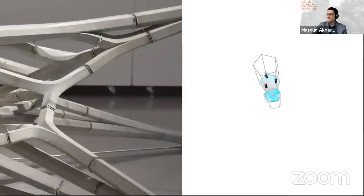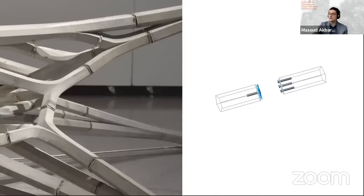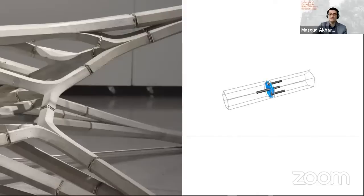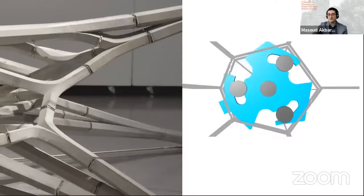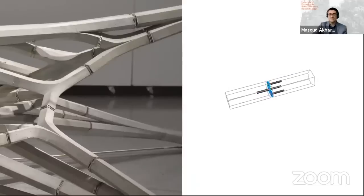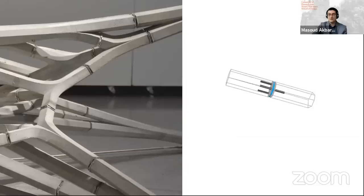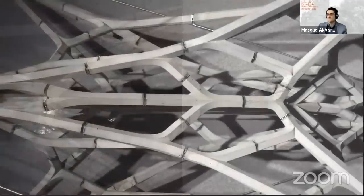Besides that, we came up with a new method of assembly, because usually in the assembly of spatial systems, the sequence of assembly becomes quite important. So we eliminated the linear members connecting the nodes, and we went directly for node-based assembly for funicular structures. But for node-based assembly, obviously collision becomes a problem. For that reason, we developed a locking mechanism so that as long as two members are available for assembly, the node could be assembled without any particular sequence during the construction. And in the meantime, the detailing allowed us to withstand certain tensile forces in the members during the assembly and afterwards. So this is the result of that construction.